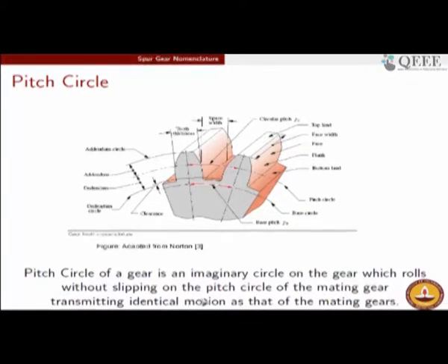So, the point is that this is where all the discussion started, that things are already conceptually there in the friction disk idea. It is just that the friction disk is not a workable idea owing to the fact that the shaft will bend and eventually break also, and therefore, we had to contrive a different application which is what our toothed wheel application or a gear application suggested.